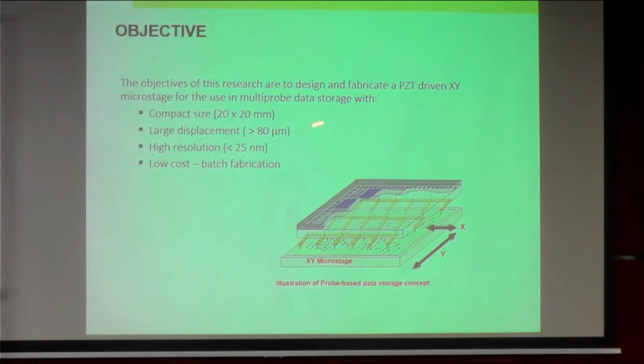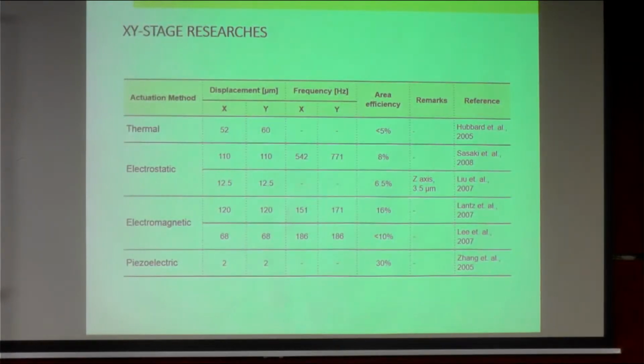So here the objective is to fabricate a PZT-driven or piezoelectric-driven XY microstage for use in data storage, with a compact size of 20 times 20 millimeters, a large displacement of more than 80 micrometers, and a high resolution of 25 nanometers, I mean the stepping of the movement, and low cost, which is something that can be realized by the MEMS process, the microfabrication process. So this is to benchmark before we proceed.